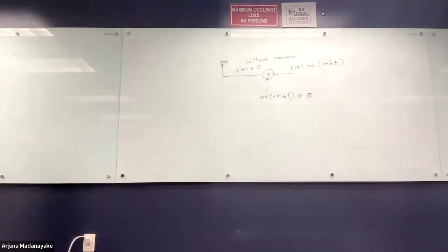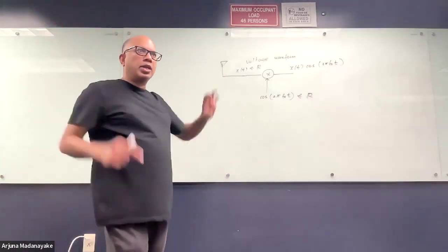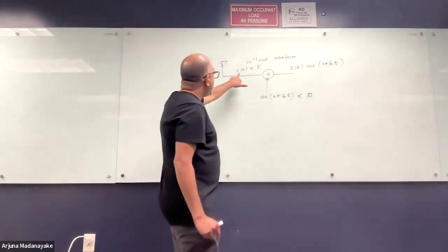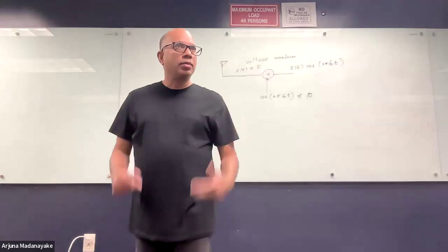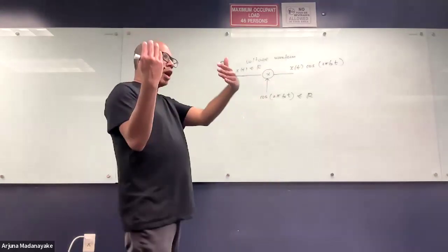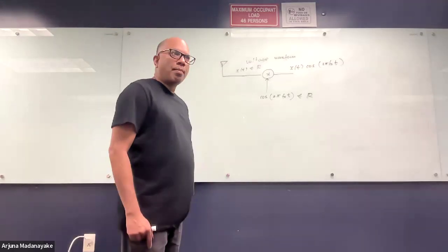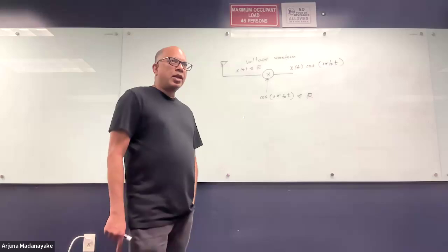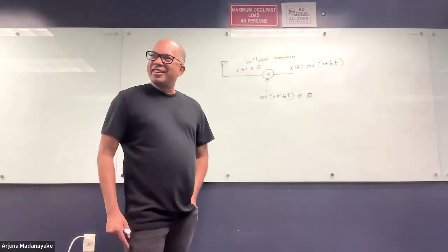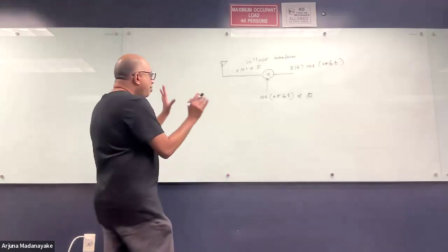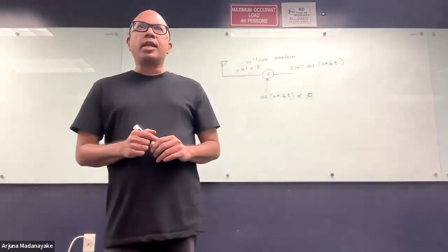So now we change the mathematical model from complex x, complex waves e to the j omega t into real x and a real waveform that's modulated. Right? Both are real. Real times real is real out. Everything's real value. So this is something we can go to the lab and build, and next week we'll show you how to actually do it. By we I mean you. You will do it.